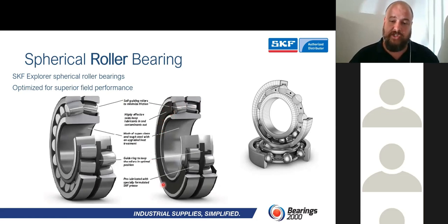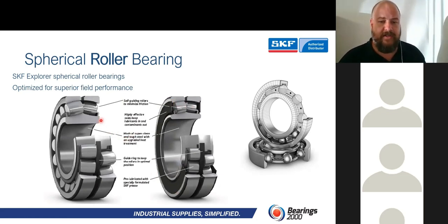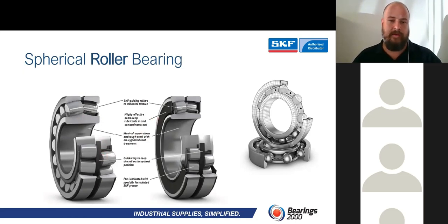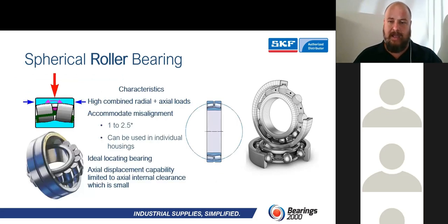Okay, this is your sealed unit. Yes, a sealed spherical roller bearing, made from super clean and tough steel with upgraded heat treatment. There's a guide ring, and what that guide ring does is, as the bearing comes into its